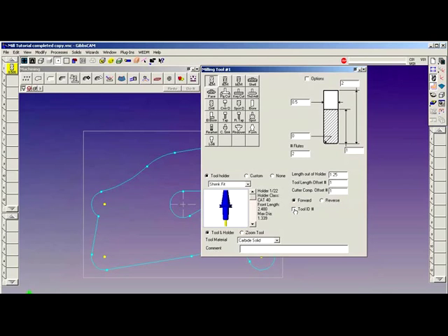In this case, I'm going to use the tools in the order of creation. In the viewport here, we see the tool, the holder. Holder selection is done from here. And using the scroll bar, we can select different styles of holders to hold that defined tool.